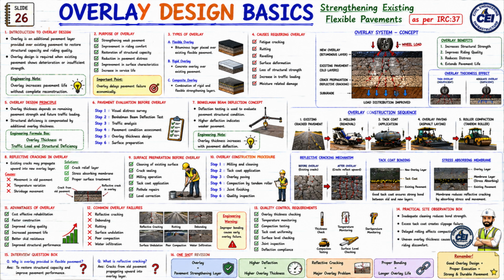1. Introduction to overlay design. Overlay is an additional pavement layer which is provided over the existing pavement. What is its purpose? Restoring structural capacity, improve riding quality. When the existing pavement becomes weak or distress starts to develop, then the overlay is provided. See the engineering note below. Overlay increases pavement life without complete reconstruction. There is no need for complete pavement reconstruction.